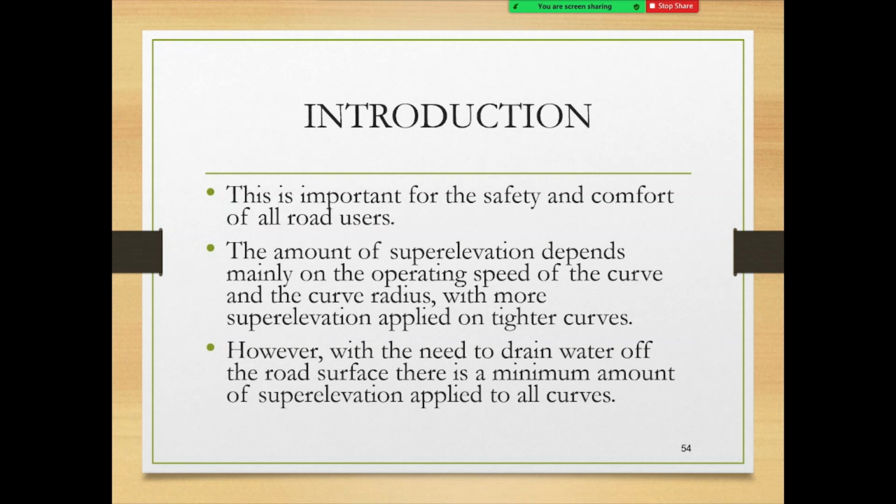The amount of superelevation depends mainly on the operating speed of the curve and the curve radius, with more superelevation applied on tighter curves. What do you mean by tighter curves? Narrow curves. The radius is narrow, right?